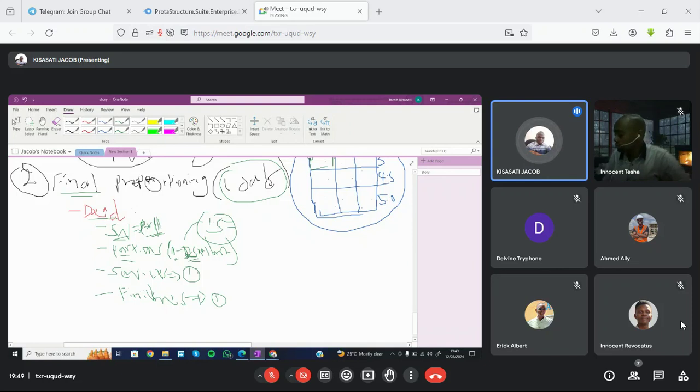Some of the buildings where you can end up assuming 1.2 or something like that, but don't exceed 2 kilonewtons. So once you get services and finishes, partitions, I have told them in a range of 1 to 2.5, and we always use 1 or 1.5. Then we are done.